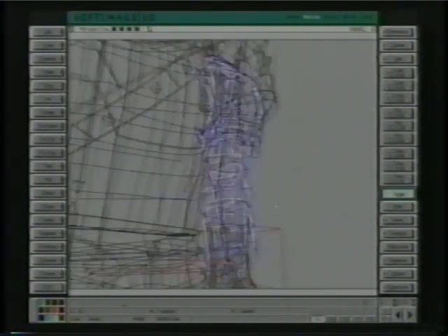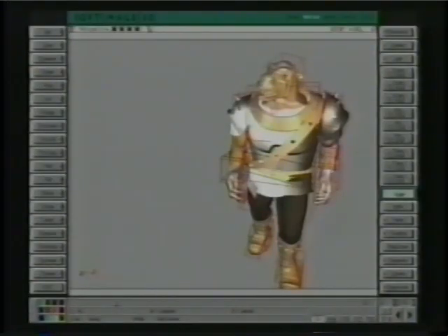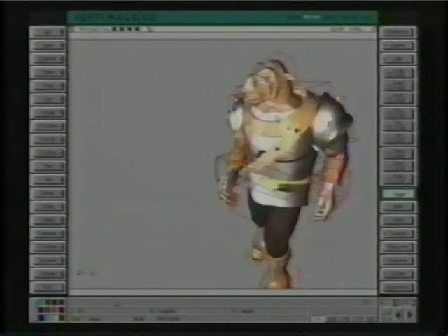So there are 2 polygons in between those 2 in this NURBS object. Now in Info Selection I can change this to something higher, and that'll increase the number of triangles that the object has. Watch that go down and up as you change those numbers. To make it more, obviously it has more polygons when it's rendered.